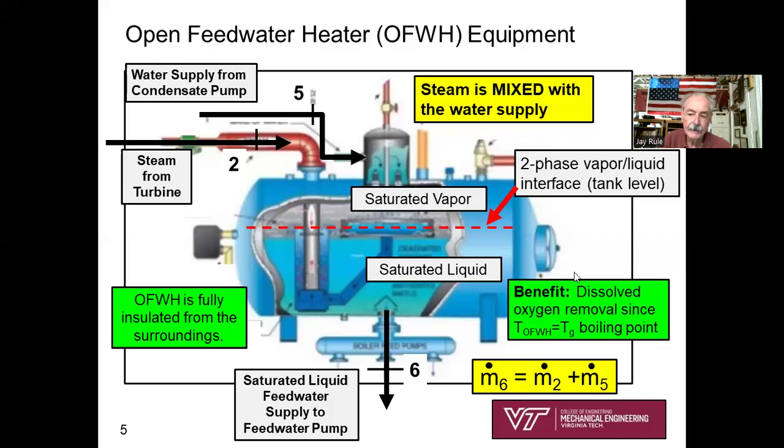A benefit for adding this device, in addition to improving the thermal efficiency, is that when you raise water up to its boiling point, no matter what the pressure is, that results in dissolved oxygen, dissolved air, being removed from the feed water, and that's very good and healthy for the boiler, so that you don't have any possibility of rusting of the steel piping inside the boiler.